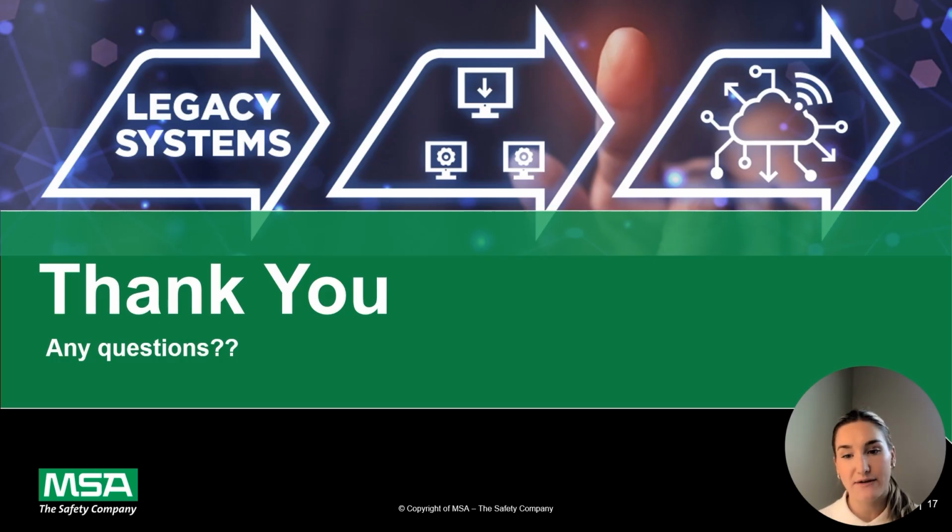So what does this mean for the long term? We don't have to rip and replace. Instead of discarding valuable Modbus devices, organizations can use gateways and edge solutions to integrate them into cloud and enterprise systems. It shifts the role from control to insight. Modbus isn't just running the plant anymore, it's feeding the data that allows smarter systems to optimize the plant.